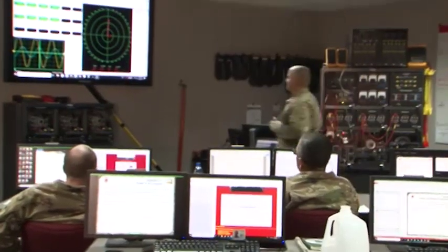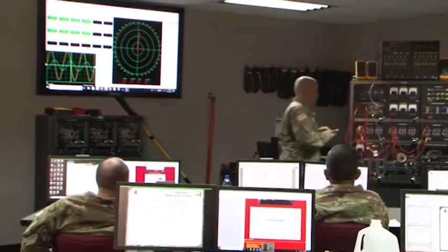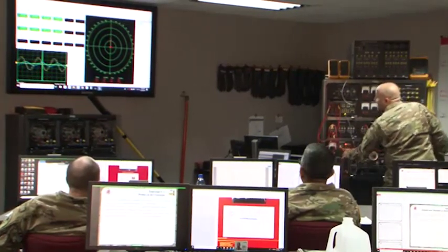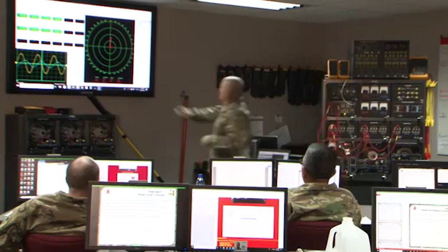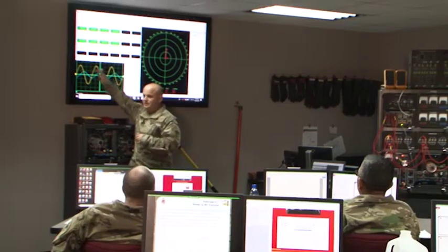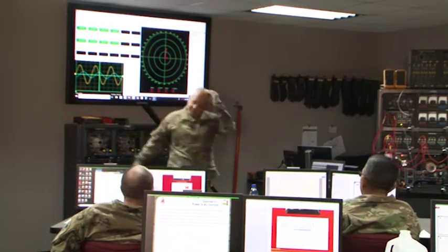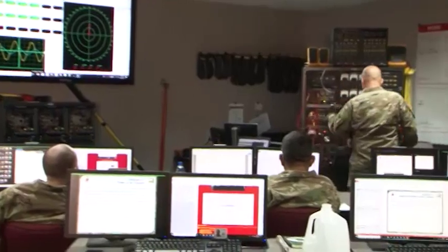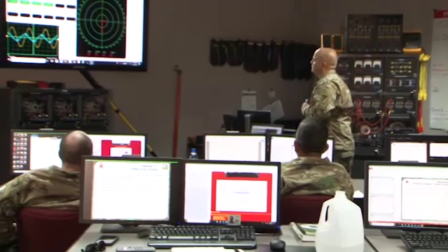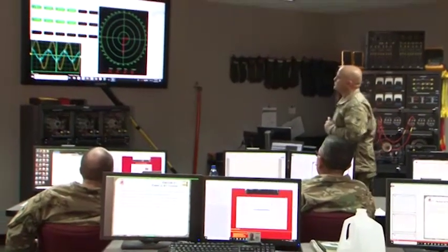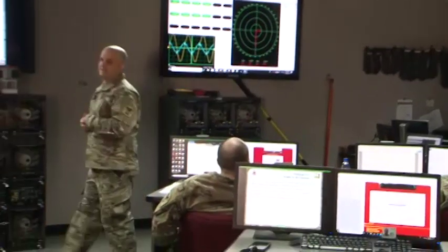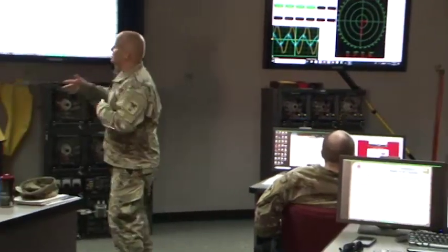So now I'll leave it like this, okay? I'm going to turn off, let's dial it down. And again, notice here, we see over here that this is peaking before this one, right? So that voltage is leading, okay? Voltage leading current, inductive circuit. So now I'm going to switch. All right, now which one's peaking first? Current. Current's peaking first. Why? Because that's the ICE. That's the ELI ICE, right? In a capacitive circuit, current's leading the voltage.